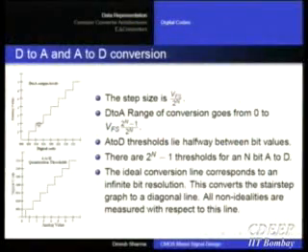Okay, what non-idealities are we talking about? Yeah, for example, quantization error, the very first thing. Okay, so if you are talking about quantization error, because of this very nature, the number or the value is not quite what that ideal straight line would have had. So when you say this is the quantization error of this D to A, then you will see how far is the output analog from that ideal straight line.